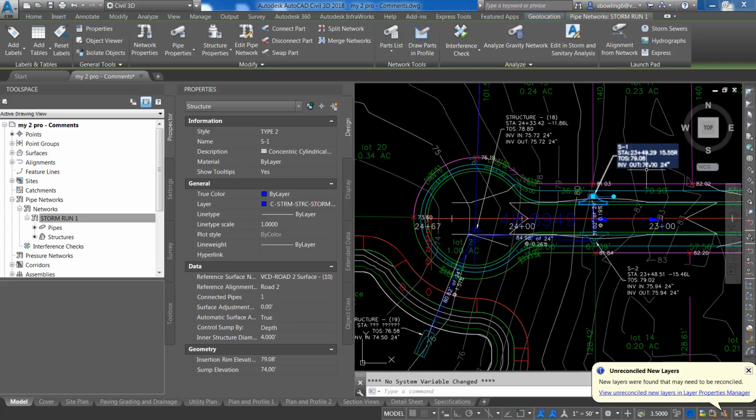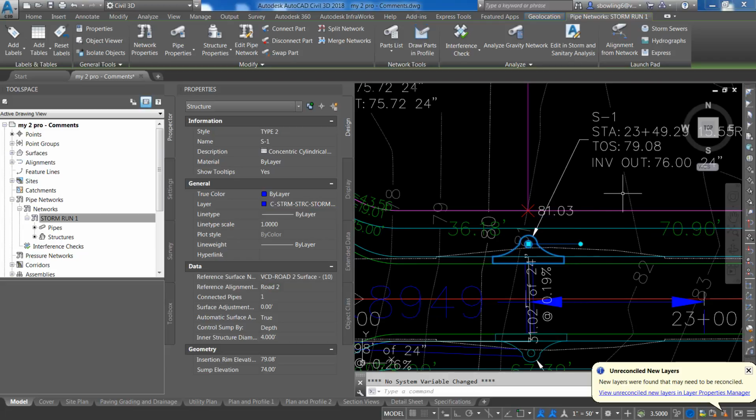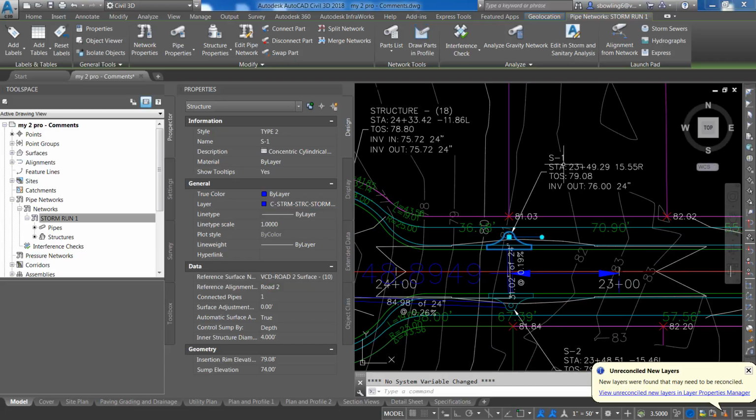So there's only 3 feet here. And it's a 2-foot pipe, so technically you don't have clearance. So I'm actually going to use the sump invert as my inverts of my pipes. So what technically you're drawing is the sump is 2 feet below the invert of the pipe. Some people do that to collect trash. I don't typically do that because it's harder to clean out.